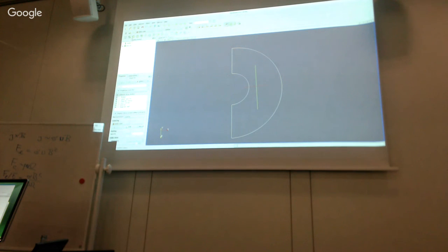So the first thing you can think about is doing some contours of scalar data. To do that, you use the first thing here. And here you are in this panel, and you have different options. Here it will list the available scalars that have been stored in the VTS file. So I don't know, let's take, for instance, radial velocity. And here you can choose the value you want.